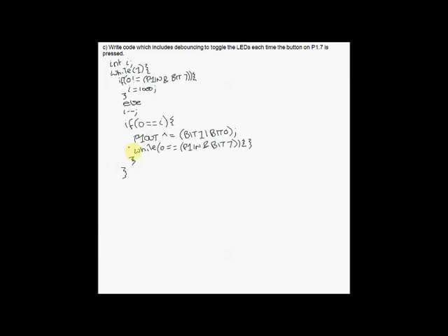Okay, there we go. So just a quick recap, we check if the button's pressed. If the button's not pressed, we want to set I equal to 1000. If it is pressed, we step into this section and we decrement I. Just missing one bracket. We decrement I, we check if I is equal to 0, we invert there, and then we wait in this section.